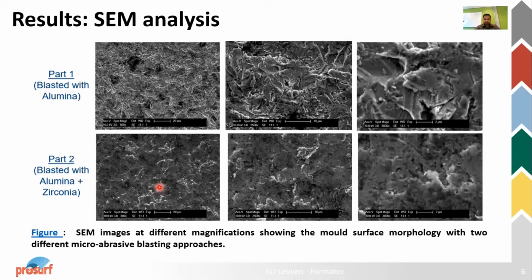First we tried with the normal metrology techniques, and we found out that it's very difficult to distinguish based on the conventional parameters like Ra and Sa, Rz, Sz, Rq, Sq, and so on.